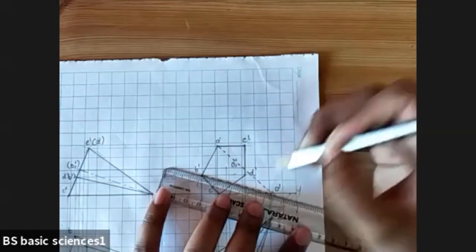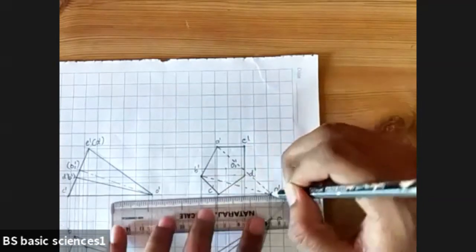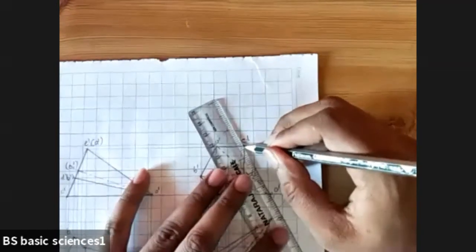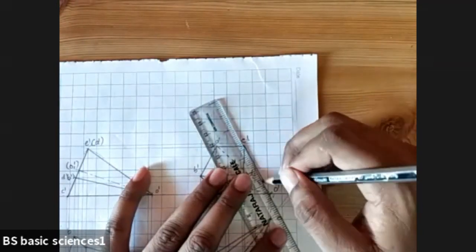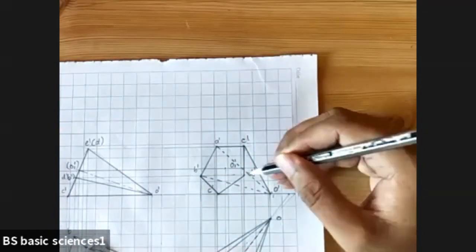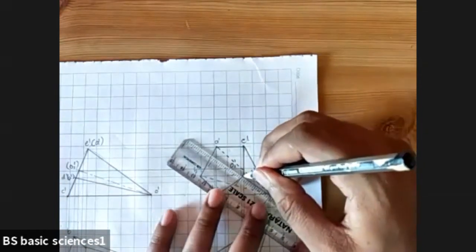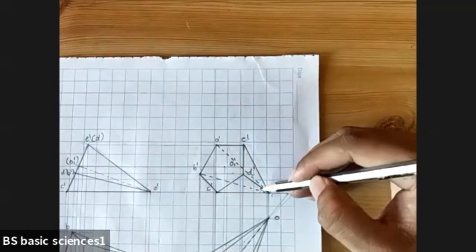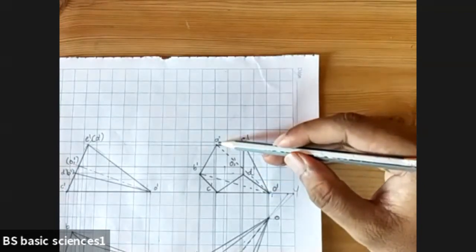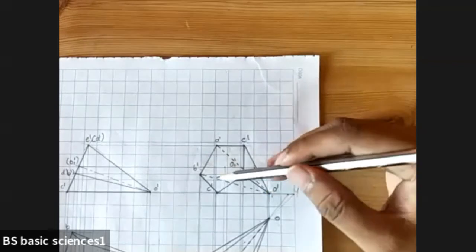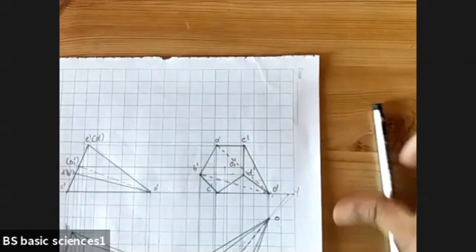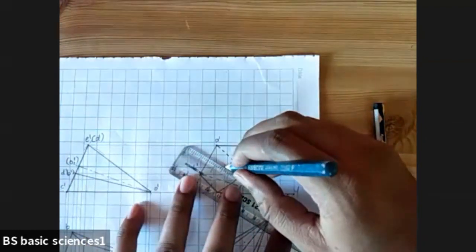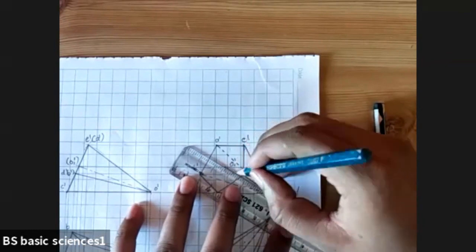Okay. Then C to O, it is passing through your XY line. It will be thick. And E to O, it is passing outside and it is not coinciding with any one of the edges. That is why it will be thick. And what about D dash to O dash? Again, that is also passing outside. 1, 2, 3. Three edges will be visible for the observer and two slant edges, that is from the A to B, A and B, it will be your dotted lines. And finally, don't forget to draw the axis, that is your O dash to O. It is thin and chain line.